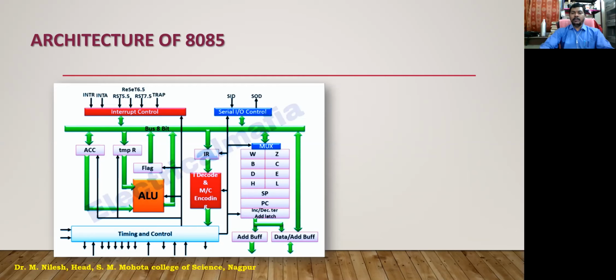Therefore, whenever we use an instruction concerned with memory, such as ADD M, that is add memory location, the data is stored in the memory location and that is to be added. For addition we require two data, so one data is always in the accumulator. The accumulator is again a general purpose register, but it has a separate specification.